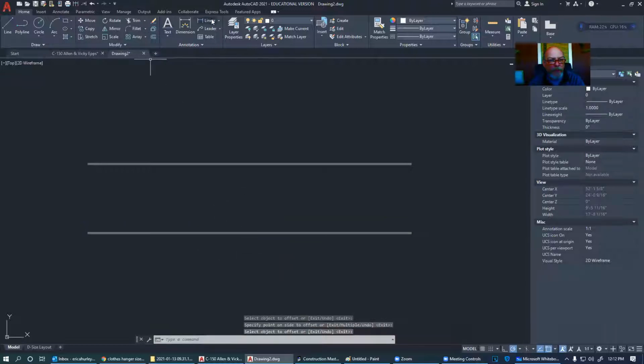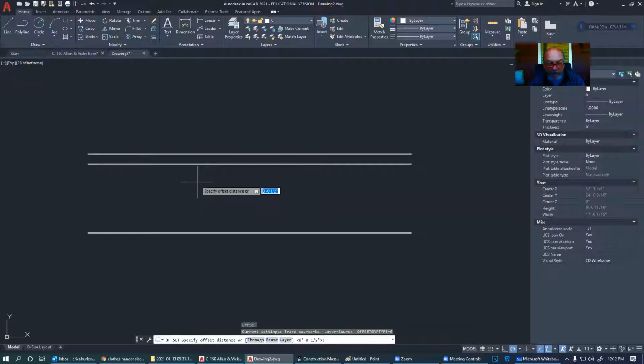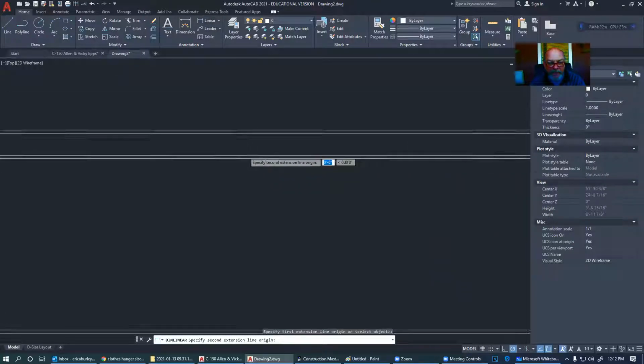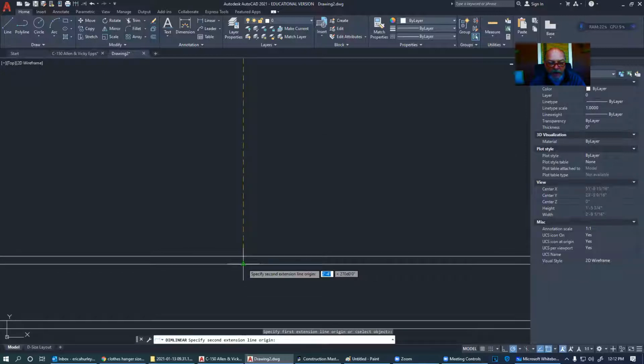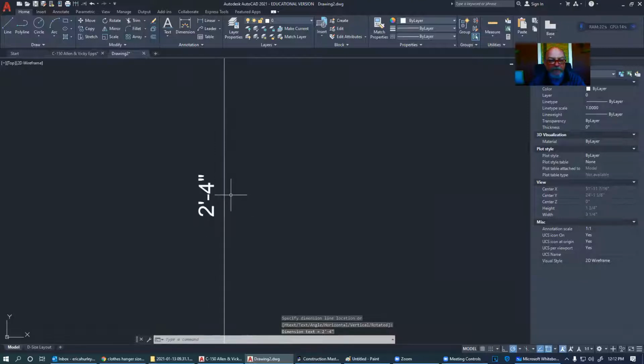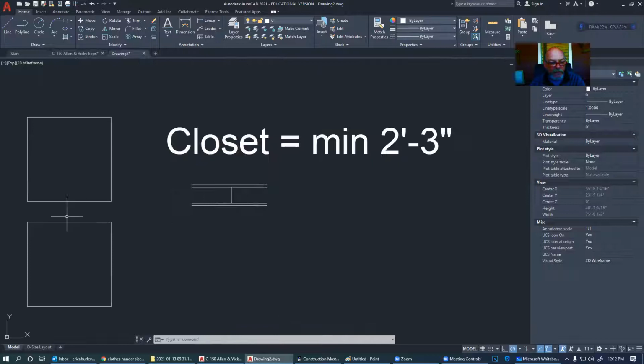And so how much space now? Remember that, let me do one other thing here. 3.5 inch. This is the stud. And this is the other piece of sheetrock on the other side of the wall. This is the stud on this side and the other piece of sheetrock. So we have the stud layer here, we have the sheetrock layers, and then we have our closet space. So we need to figure out from face of stud, remember that we're not telling the contractor the face of the drywall. We need to have a bare minimum of 2 foot 4 inches on the insides between these two.